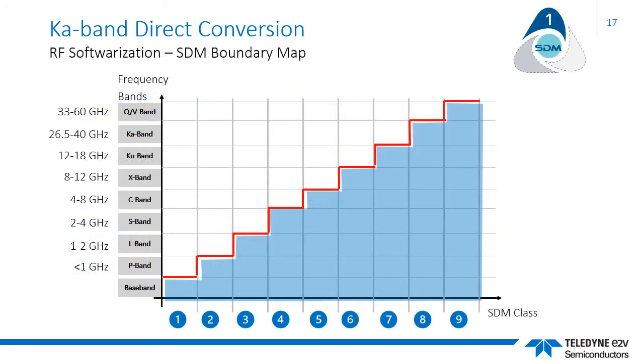As further introduction to this segment, I want to highlight that for a sampling solution to work into the Ku or even the Ka band, there's still a significant frequency enhancement needed. Today's widest bandwidth solution is the EV12AQ600, which can provide direct access into the C band as we've seen previously. However, the K bands sit at between 3 to 6 times higher frequency in the spectrum. So how is this rather significant gap to be bridged?